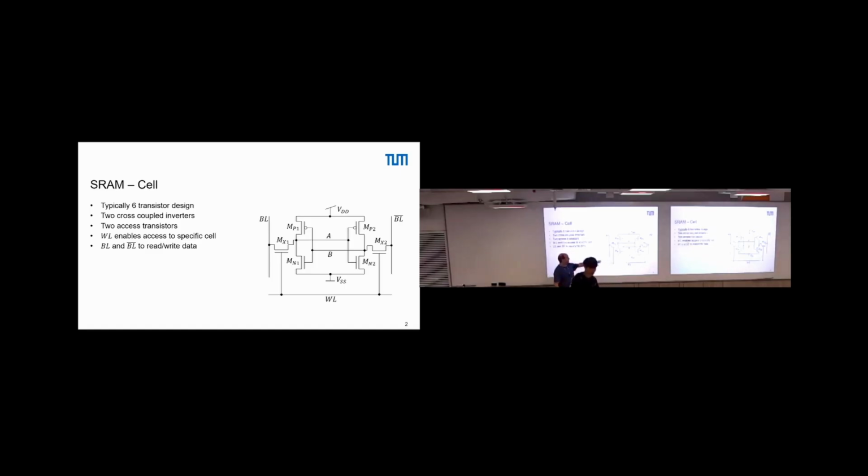Yeah, but a flip-flop is already larger than this circuit. If we have just a single bit that we need to store, this here is still smaller. So why should I use a flip-flop if this is smaller? I could always go for that, right? If it would work like this, yes. The problem is this cell is only effective if you have small transistors. If you have small transistors, you can hardly drive large loads.